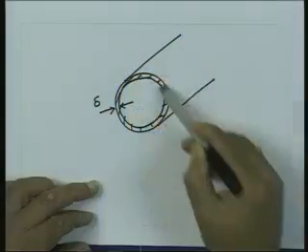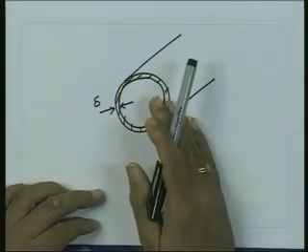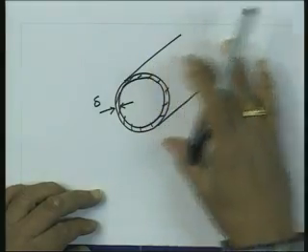So because of the skin depth, the resistance now becomes a function of frequency. For a given conductivity, as the frequency increases, the skin depth reduces. As the skin depth reduces, the area of cross section over which the currents flow reduces, and because of that the resistance of the conductor increases.